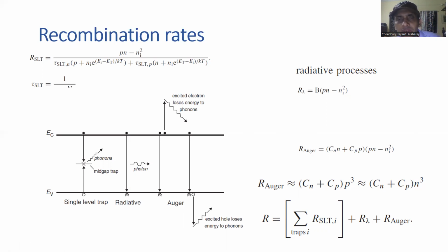As we try to make the photogenerated carriers drift and get collected in order to get electrical energy out of these solar cells, these recombinations try to hamper that process, and so we typically need to minimize recombinations. As we mentioned, the radiative recombination re-emits an above band gap photon, and that photon can be reabsorbed, so to some extent radiative recombination processes aren't all that bad.